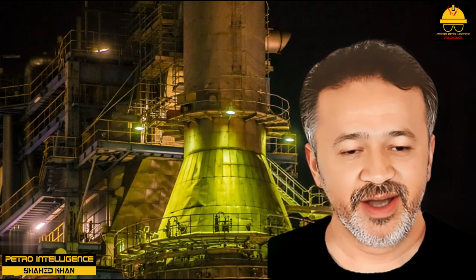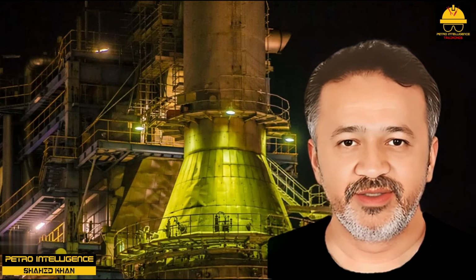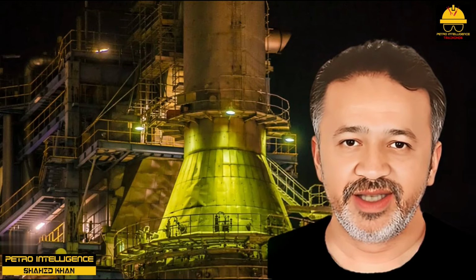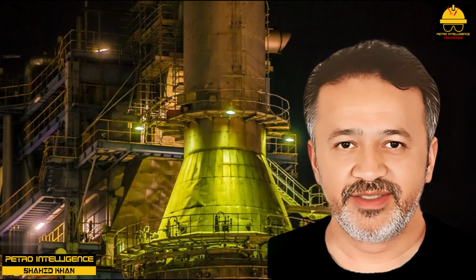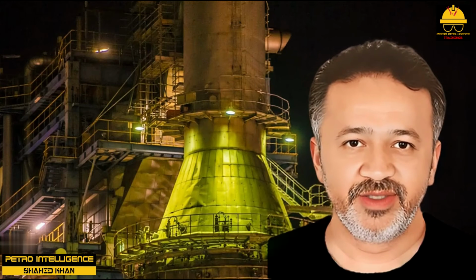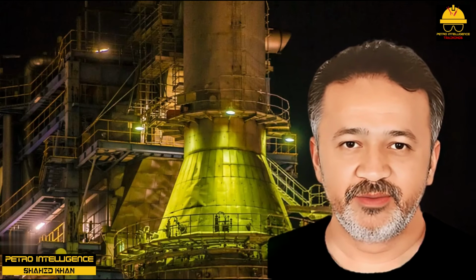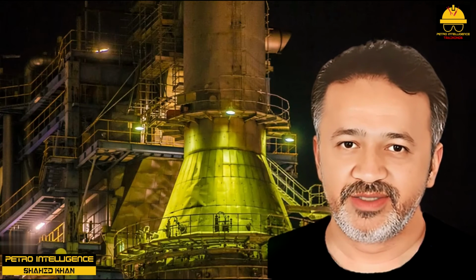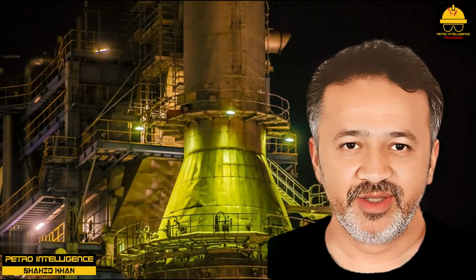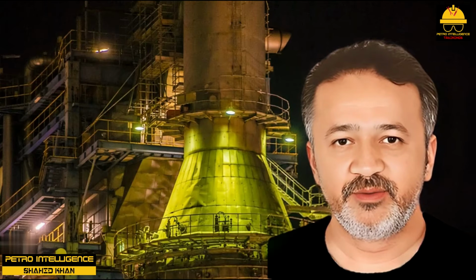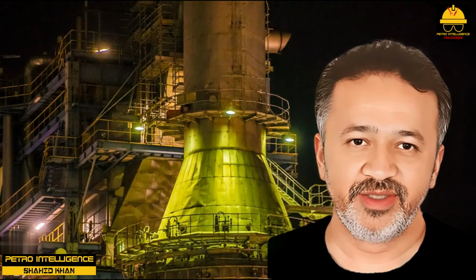Using the concept of absolute combustion in operations, the only correct oxygen target is that firebox oxygen content that maximizes the process site heat absorption for a given amount of fuel, or if you prefer, we could say it is that firebox oxygen target that minimizes fuel consumption for a given process site heat absorption.